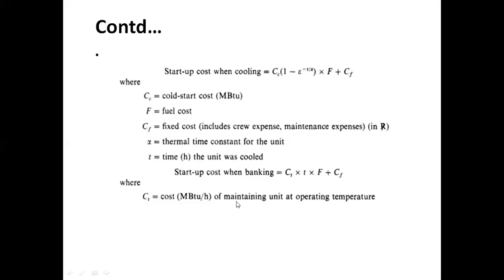Startup cost when banking is equal to Ct into t into F plus Cf, where Ct is the cost in MBTU per hour of maintaining the unit at operating temperature. So these are the general equations for the startup cost of cooling and the startup cost when banking.